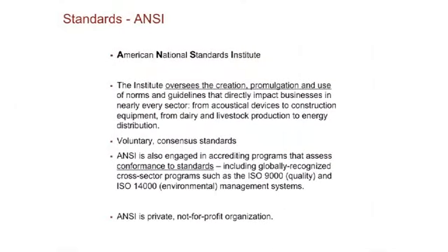Again, we have heard it so many times in different contexts. For example, if you look at this OSHA part 1910.269, the references of OSHA go to ANSI/IEEE C2, which is the National Electrical Safety Code. It references NFPA 70. It references NFPA 70E, which is a safety requirement for grounding, for arc flash, and PPE equipment, and so forth. So now this is written into the CFR.